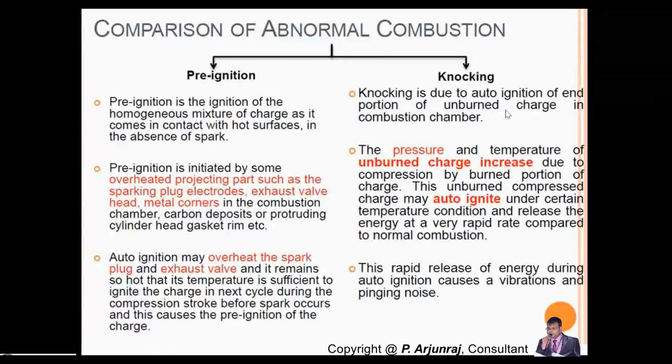The pressure and temperature of the unburned charge will increase due to the compression by the burned portion of the charge. So what is important is that auto ignition happens in knocking. The burned gases travel with some velocity, there will be some opposition, and the pressure in the reverse direction will collide. The collision happens between the unburned charges. For example, if an unburned charge is traveling from top to bottom, a similar unburned charge will also travel from bottom to top. Both the upward and downward movements collide with each other,